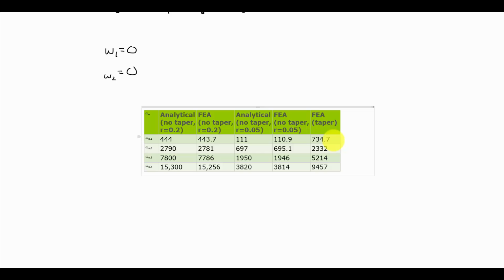Now, again, unfortunately, we are only getting a rough validation here. Is our result from the finite element correct? We really don't know. We can't necessarily show this is correct, but we can have some confidence in trying to get an upper and a lower limit, or at least a magnitude estimate based on the analytic solution, which was the exact solution to an approximation of the problem, which matched the FEA version of that approximation to the problem as well.